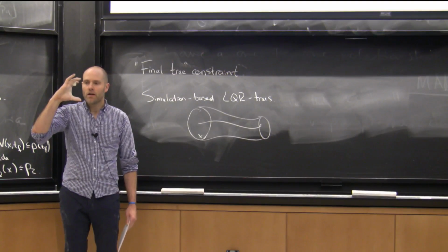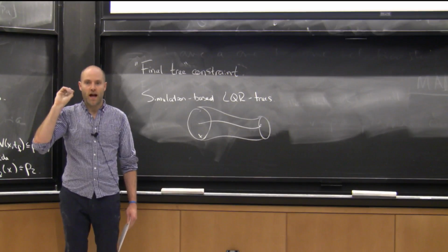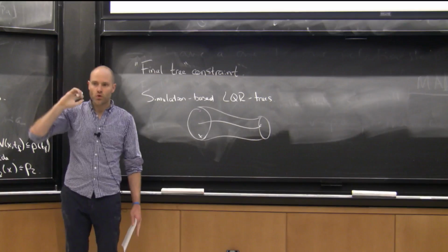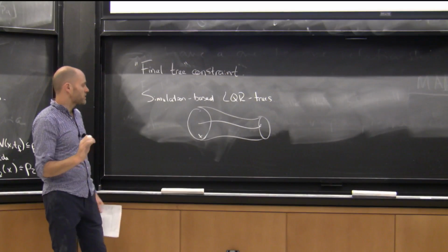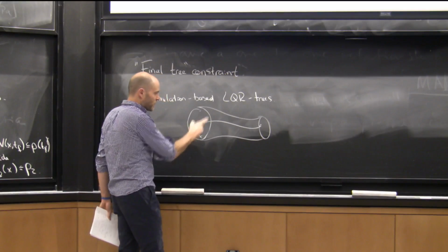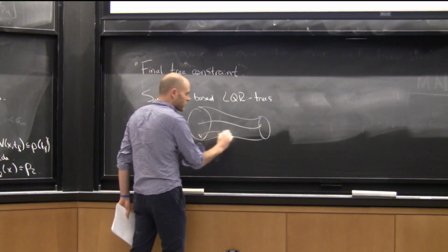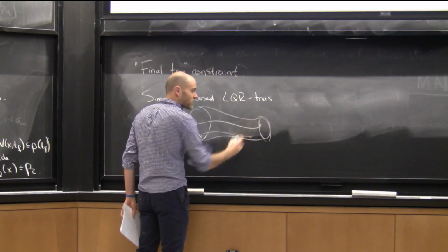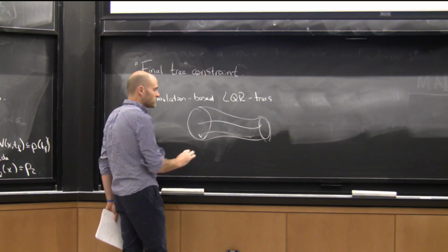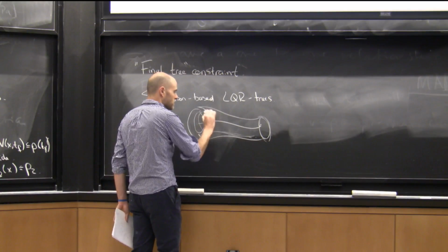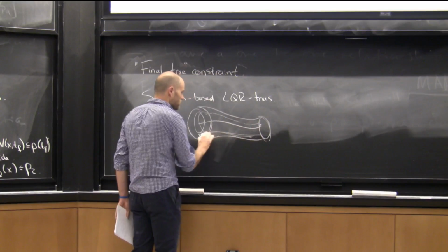I just have to find one of the funnels that says I'm stable. I will stabilize this initial condition. You can impose a total ordering based on some simple heuristics to make sure you don't chatter. But I pick some funnel that it says is good, and I start executing it. You can do this in simulation, of course. If it achieves the target, all is well. You leave the funnel alone. If it doesn't achieve the target, you can actually reduce the funnel based on that sample.